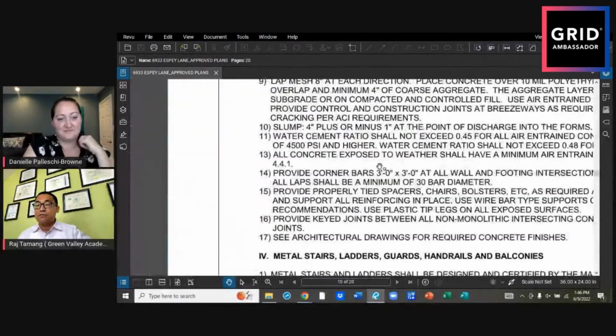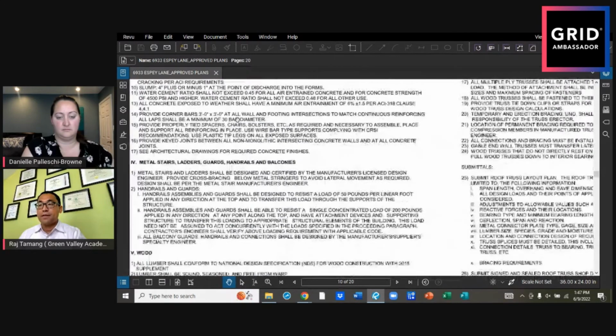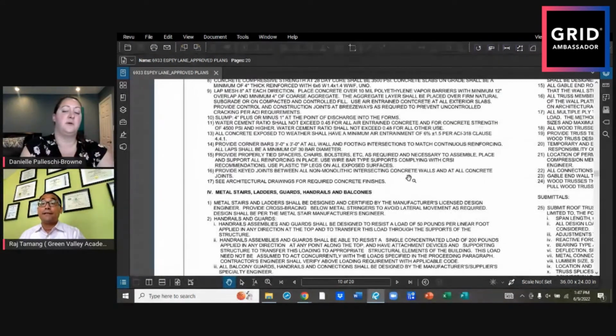You have air entrained concrete, which has a specific use, and sometimes you use concrete for different applications, like high security places or even a blast resisting structure. That's why the code has whole different sections of requirements for concrete with different applications. So exterior concrete, like patios, sidewalks, walkways, retaining walls, would all of that need air entrained concrete? Yeah, exactly, you have to have that.